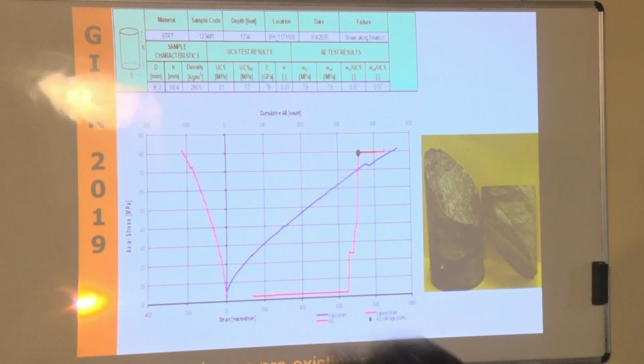So again, the dynamic measurements using P and S waves and the elastic modulus and Poisson ratio we measure in the test really measure two very different strains. There are, I would say, relationships that have been developed to relate one to the other. But really those are empirical relationships, so you need to pay a lot of attention when you're going to model, on what is the value that you are going to take.